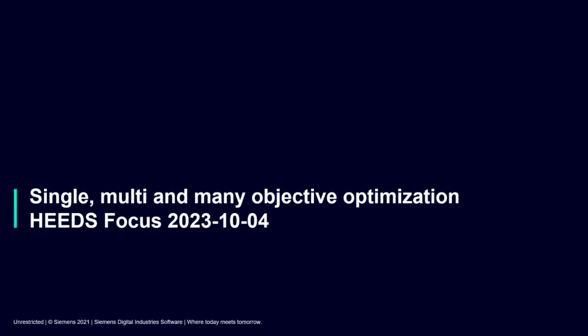Generally speaking, people use more generations than individuals in the population, because the more generations you have, the larger the chance that the optimization has converged, while a large number of individuals means that you have more individuals that can search for information, so you can cover the Pareto front better and also explore larger parts of the design space.